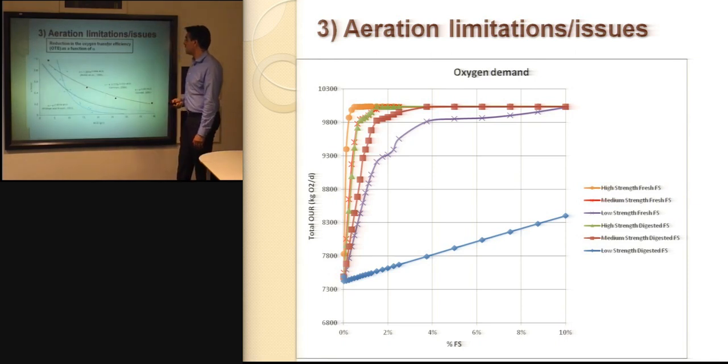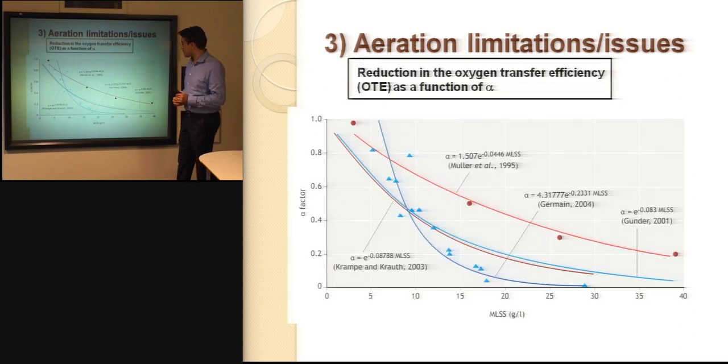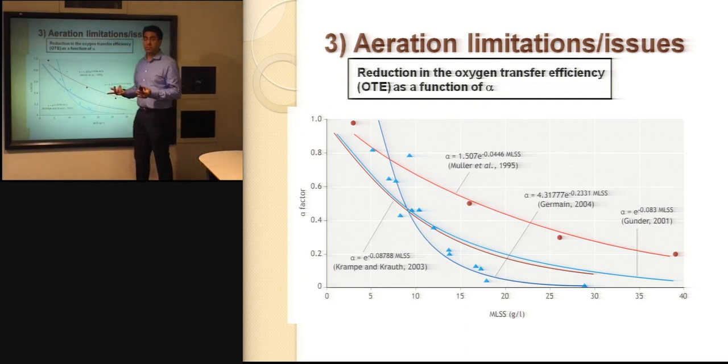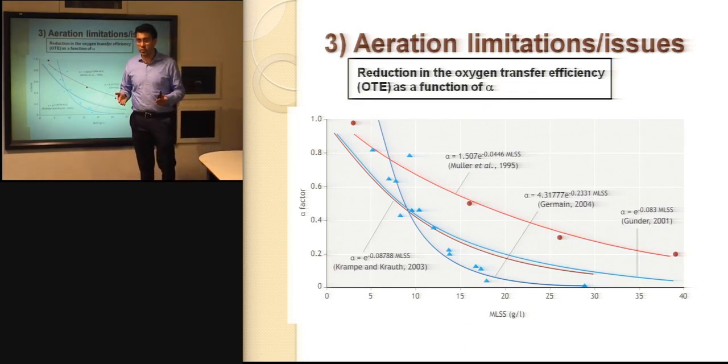Basically, because it has been reported in different research studies that the total amount of oxygen that can be transferred from an oxygen supply system to the bulk liquid depends on the amount of total suspended solids present in the aeration tank.